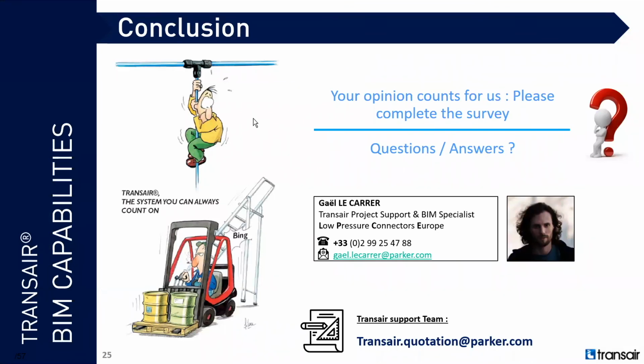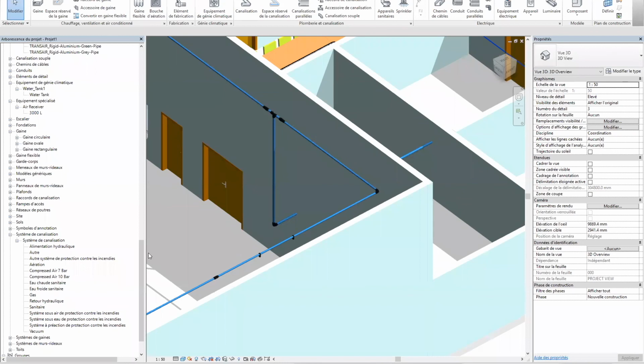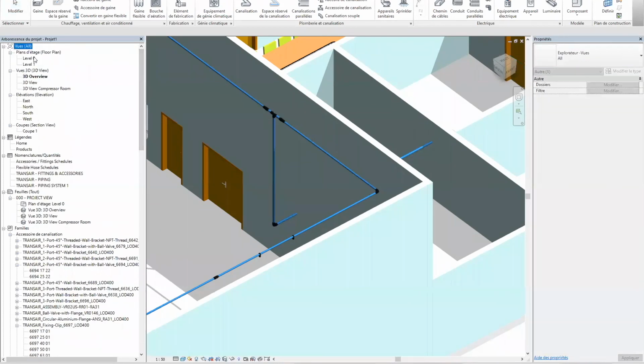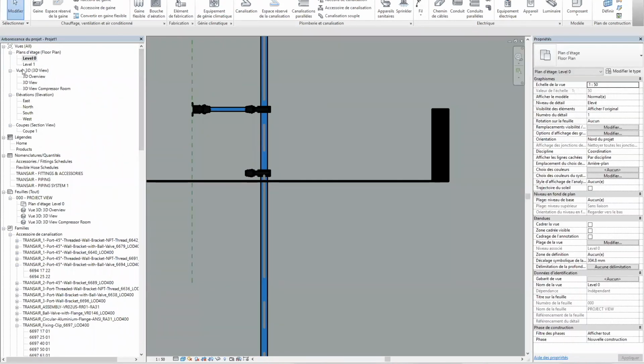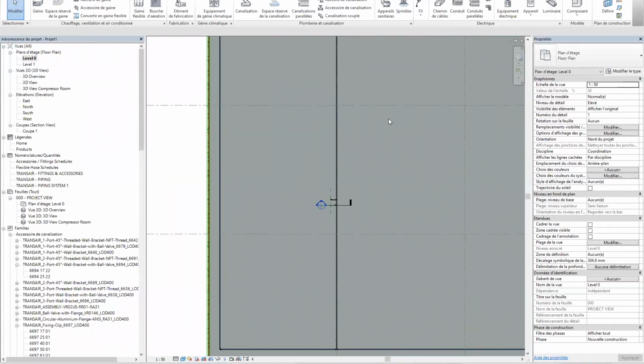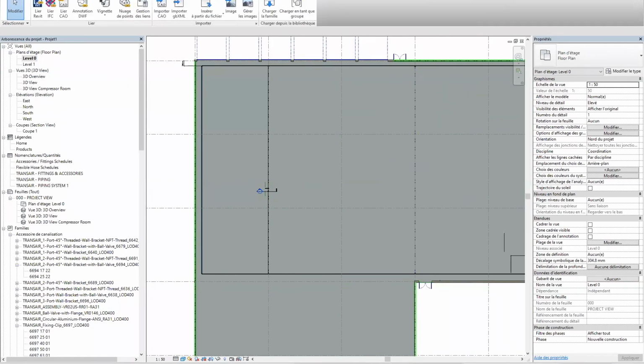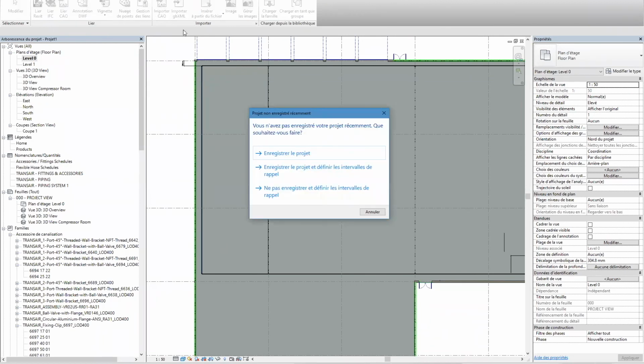Yeah, so regarding importing a CAD file, it's completely possible to do. You will need to be on the floor plan, either ground floor or another level, and you go in the Insert tab, and there you've got either link a Revit file, IFC, a default BIM file, but you also have CAD, so AutoCAD files, you can import them.